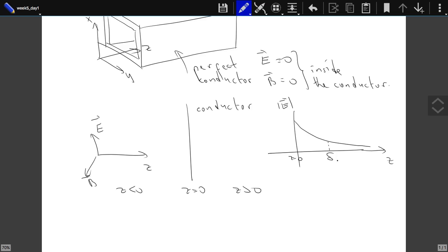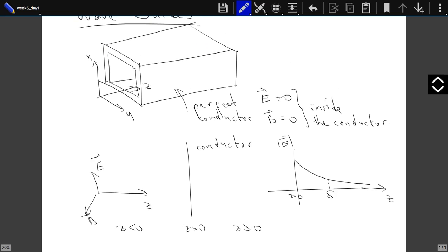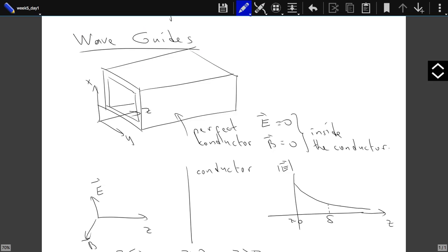So that's the case we want to study. We don't want the electric field to leak out, let's say. The electric field is all confined inside. Well, for that to be confined, we just wanted some thickness. Well, for a very good conductor, that thickness is very small. I mean, a very thin sheet will also be able to prevent any electromagnetic field leaking. In the case of a perfect conductor, the skin depth is 0.